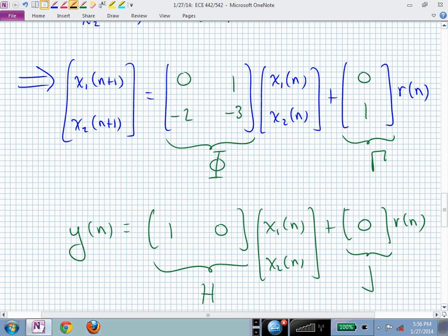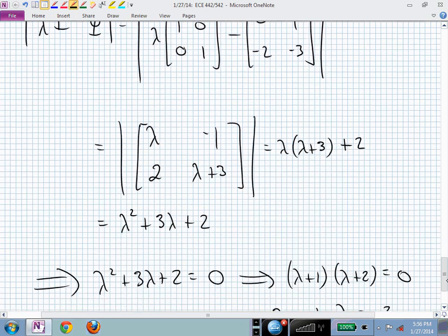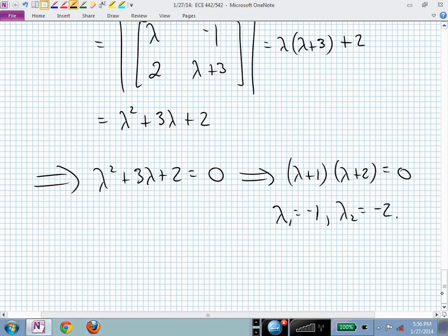Based on what we will do in a little bit, we will convince ourselves that if any of those eigenvalues have a magnitude, so if they're complex, you find the magnitude of those complex numbers, if any of their magnitudes exceed the unit circle, then they're going to go unbounded in time, and it would be an unstable response, and that's what this guy is saying.